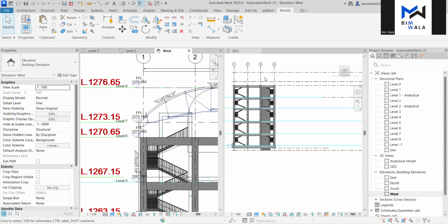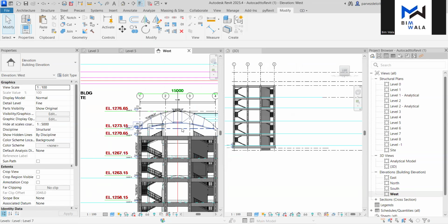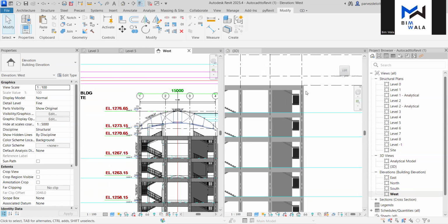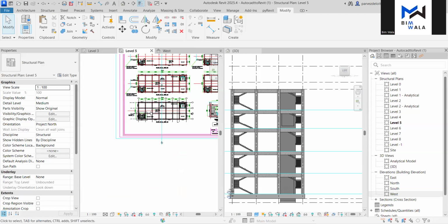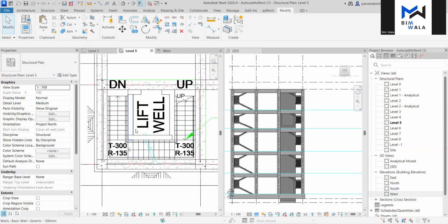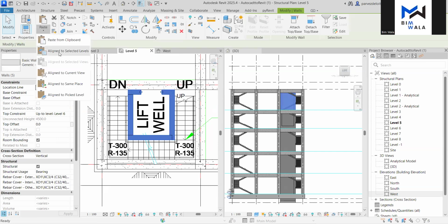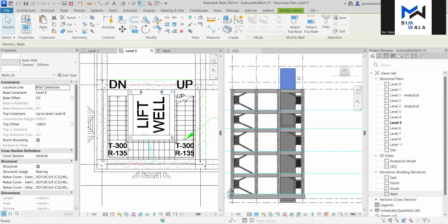So हमें एक floor और ऊपर जाना है, so that you can go to this level, roof level पर, आप जा सकें, वहां से if you want to carry out some inspection you can always do that, right? So what I'm going to do is basically I will select level 5. I'll go to level 5. I will place this. I have selected this. Now I'll go to copy and then paste it to which level? Level 6. Okay. This is at level 6.